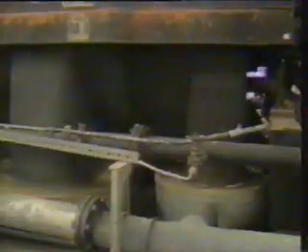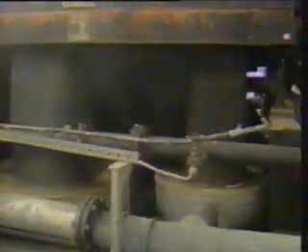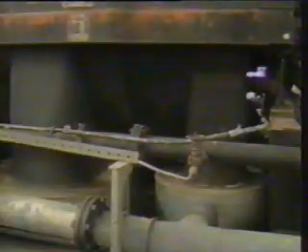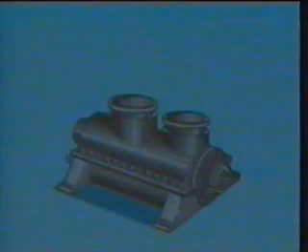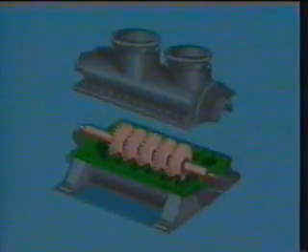The main inlet and discharge nozzles, side connections, and other attachments are often built into the lower half of the casing. This allows the upper half of the casing to be removed for ready access to the compressor shaft, impellers, and bearings for internal inspection and maintenance.